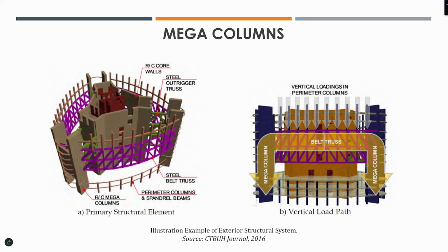So another configuration here. This is now 3 mega columns with these braces around that. And then this is important. You should notice this one. The internal columns which are coming to the floor are coming and resting on this one, but they're not going down. So they transfer the load to the mega one, and then a new set starts again.